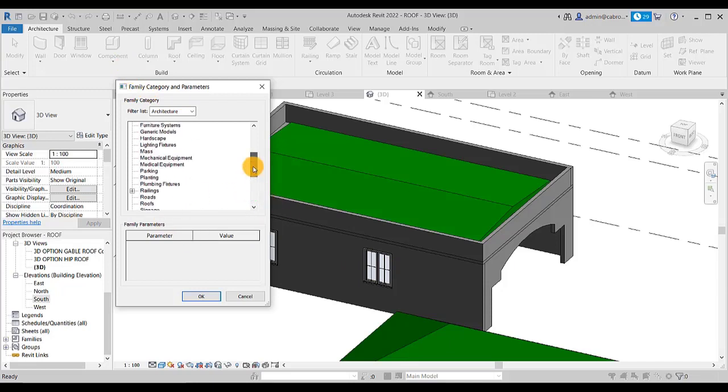It comes out nicely. But let's say we are not so sure of where to put the moldings around here. Because when I pick a wall, it means that I want to model a wall-hosted element, so that when I finish, it is hosted by the wall. If you have roofs, it means I want to do something that can be hosted by the roof, or something that surrounds the roof, or probably when I do floor, something that ought to be placed on floors or hosted by floors and stuff like that. Let's choose generic model for our case, and start the whole process. So I select generic models, then I click OK.